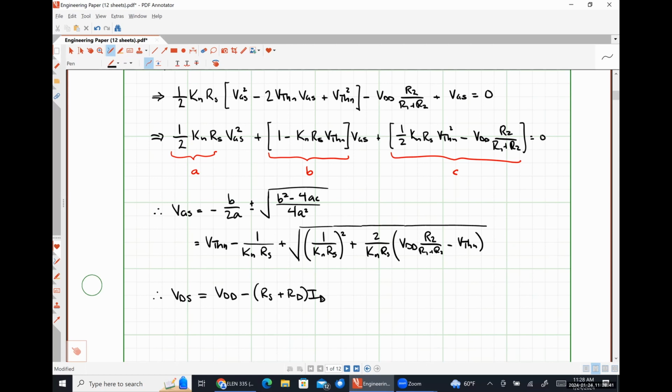And so we simply compare things, right? So if VDS is greater than VGS minus VTH, we don't have any more work to do because our assumption that saturation mode operation was happening is correct. And so we have effectively found our DC bias point. If VDS is less than VGS minus VTH, unfortunately, we have to redo literally everything, now assuming that the device is operating in triode region. Okay, so that's our check.